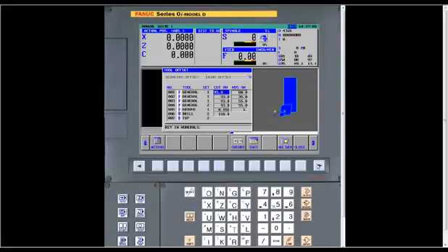All right. Now the next one, cut angle and nose angle. These are very critical, because if we put the wrong information here, you get all kinds of bad information when you actually make the program. As I said, the tool that I have in my machine, it's an 80-degree diamond tool. And with that type of tool, it always has 5 degrees of clearance on the front side. So if it was perfectly square, it would be 90. So you take 90 and add the 5 degrees of clearance, and that's where you get to 95. Then the nose angle is the actual shape of the insert. Not the clearance relief on the backside, but the actual shape of the insert.